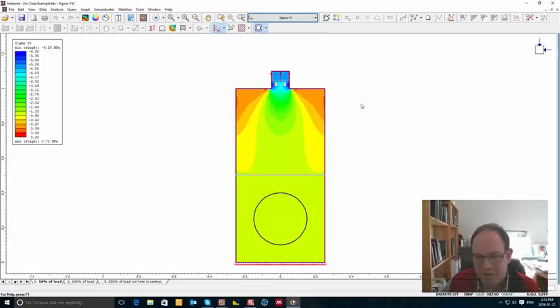Again, because it's a geomechanical modeling software, tension is negative. So we got a light blue across the top here, which is around 5 MPa negative, so that looks right. Okay, that's exactly what we expect. And if you remember from class when we talked about St. Venant's principle, the stress distribution becomes uniform after a length equal to about the width, which is somewhere around here. And you can see it does become about uniform.